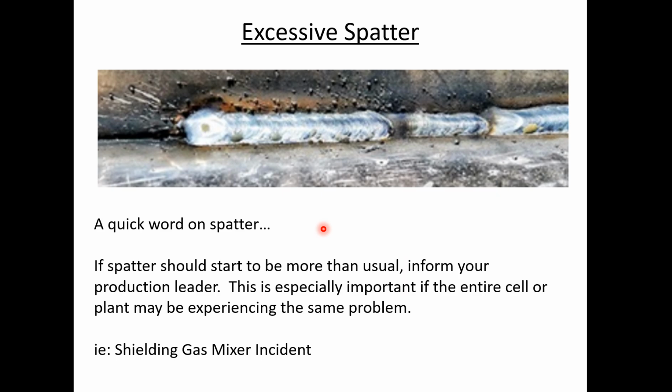So there's a lot more to having spatter. I only touched a little bit before on the importance of spatter-free zones. This is where you have something that's going to be rubbing on that zone, probably a piece of rubber of some kind. If there's spatter underneath it, that little piece of spatter will start wearing a hole. We want to do everything we can to make sure we're not interfering with the E-coat later on. And having spatter-free or a very controlled spatter makes life a lot better.